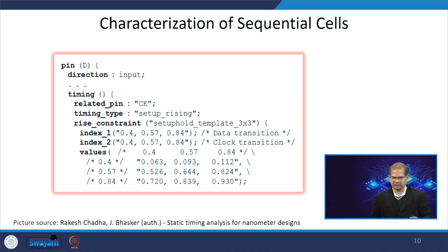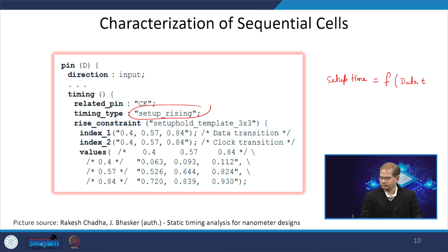This is the timing library corresponding to sequential circuits such as a flip flop. This is the setup rising, and in this case your setup time is a function of data transition time and clock transition time.